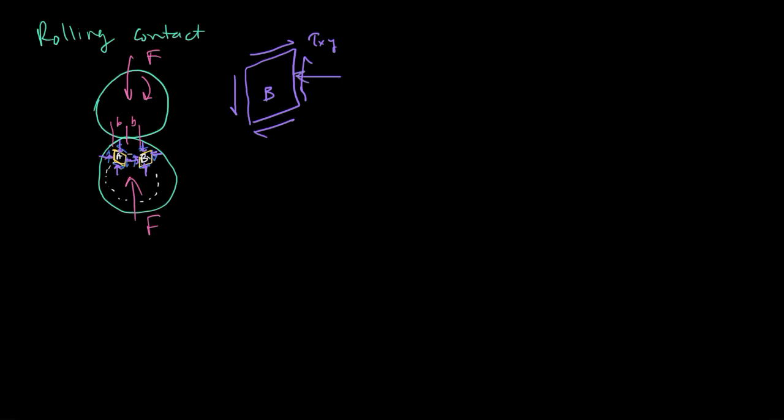But we also have these compressive stresses that show up. And A will look just like this, except it'll look as though it's reflective, and so we basically go from this state of shear to the opposite state of shear and have fully reversed shear. And instead of calling this tau xy, I'm going to call this tau max to be consistent with that graph.